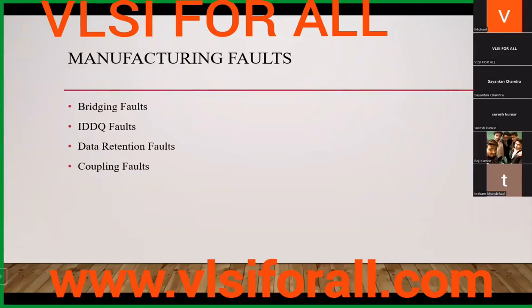Coupling fault is when, as you know, memory has a row-column 2D structure. Coupling is when one cell changes its value, so the neighboring cells are affected. For everyone else, during our memory programming, if we program one particular location, because of that programming any other cell changes its value. That is what we call a coupling fault.